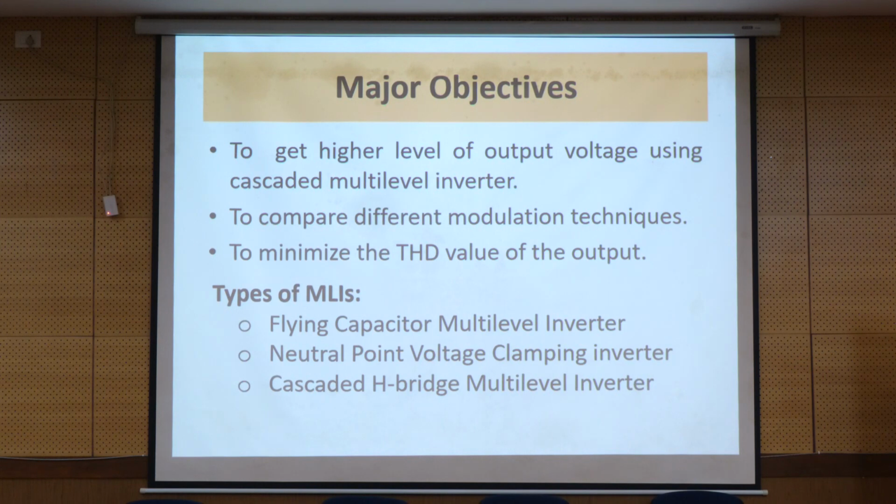So there won't be much additional effort in terms of the switching pattern, and the structure development is going to be the same. If there is any faulty module in the system, we can easily replace that module and run the system. That is one advantage. Also, since the switching pattern and structure are the same, the design of the heat sinks and gate driver circuits is all more or less the same. This is the advantage that we get.